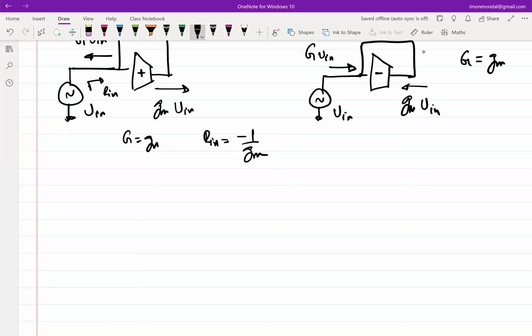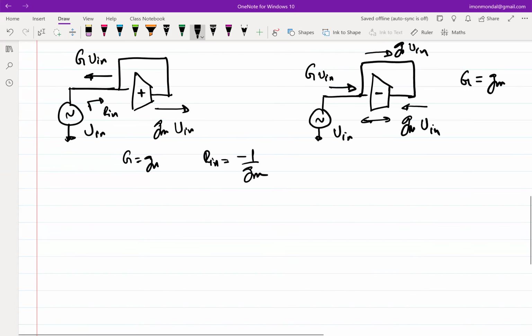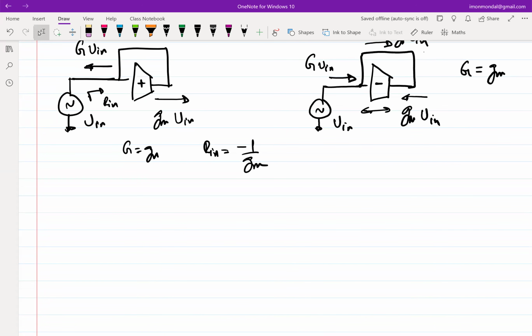So I essentially have a voltage controlled current source. I mean, this is basically a dummy for a transistor, right? I have a voltage controlled current source with a negative sign, which means inherently inside, maybe you can think of a common source amplifier embedded inside. So what do I need to do to get from a negative sign to a positive sign if I have one negative sign VCCS available to us? Add another, right? One more flipping will do.